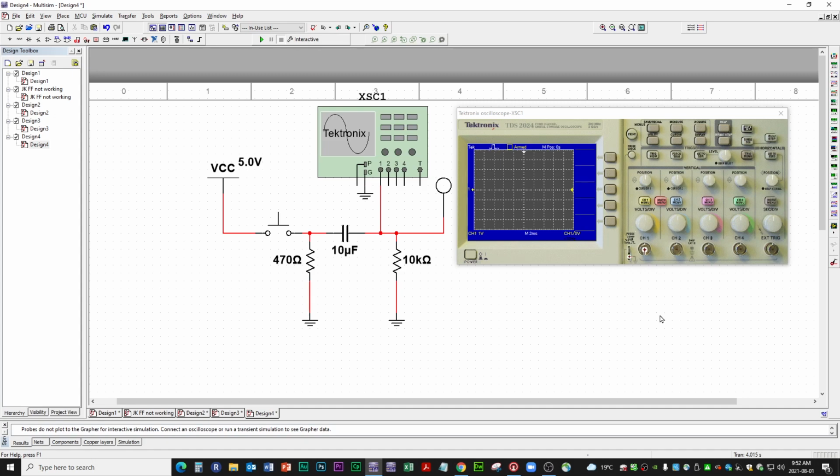Let's just catch a single sequence. So here is the sequence of events that we're going to do. First, you gotta turn this thing on. Now, the first thing we're going to take care of is that we have to set the trigger to the normal mode, not automatic mode.